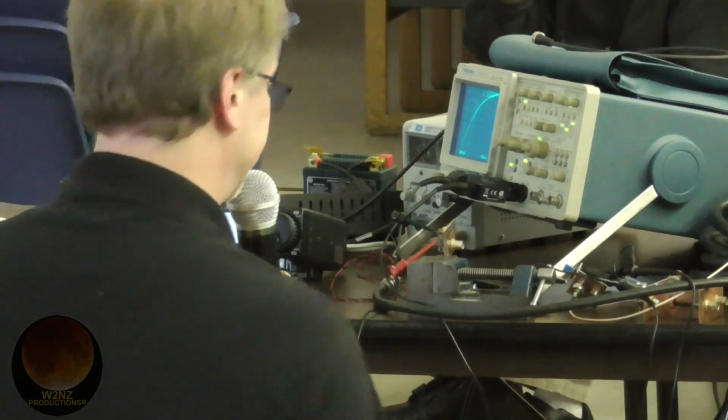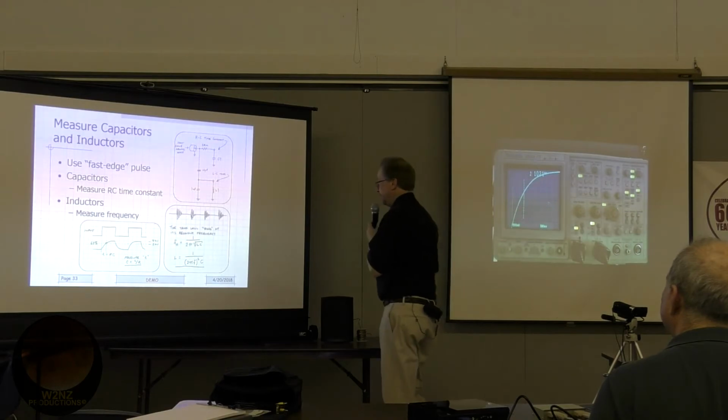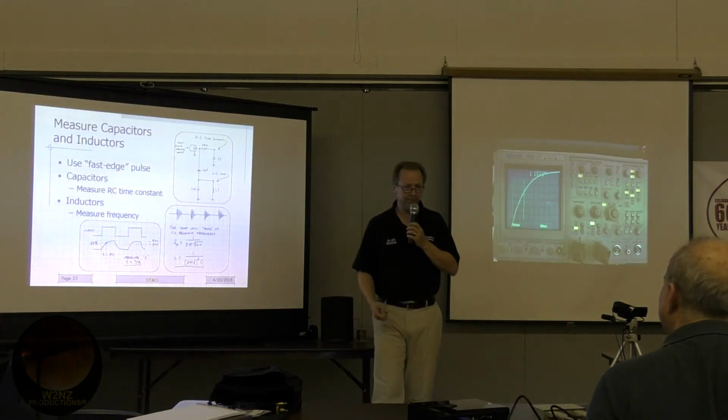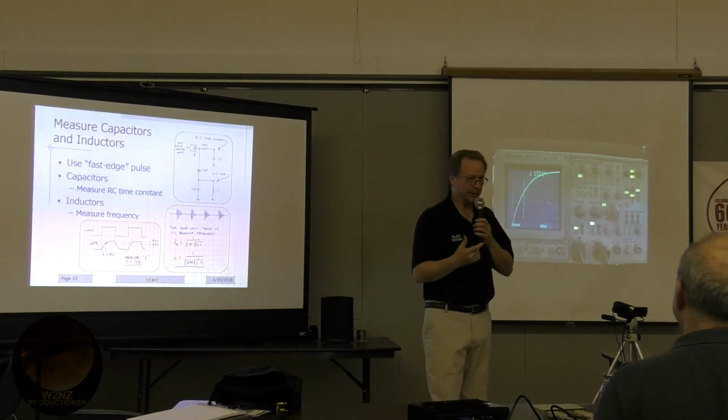Pretty cool. So now something else we can do: how can I measure unknown inductors? One neat way is to ring them. If you put an inductor and a capacitor in parallel, it makes a tank circuit.